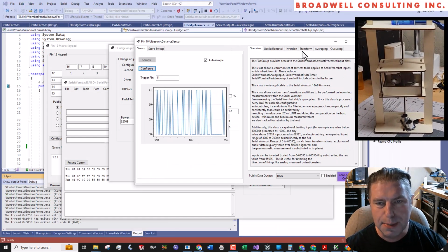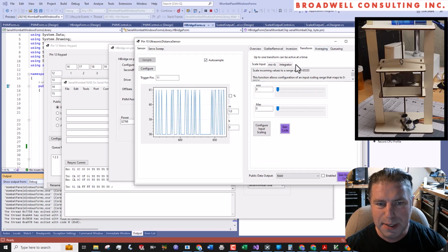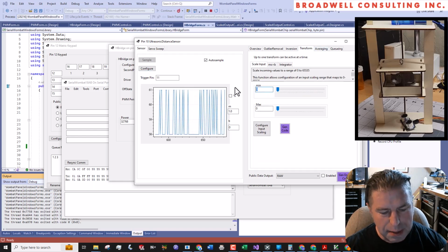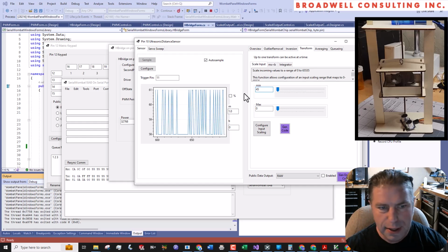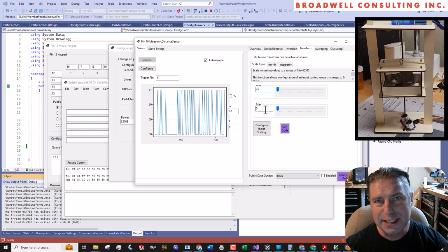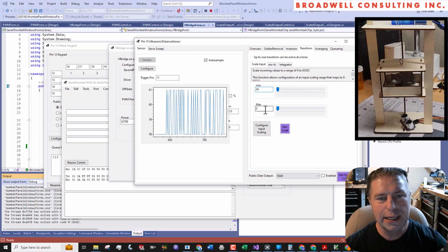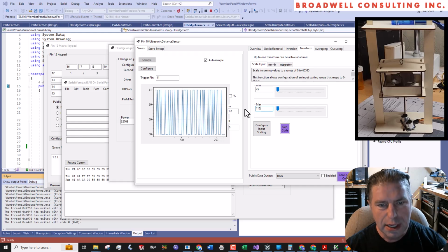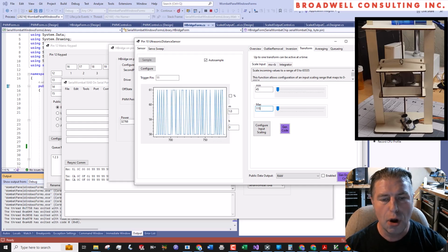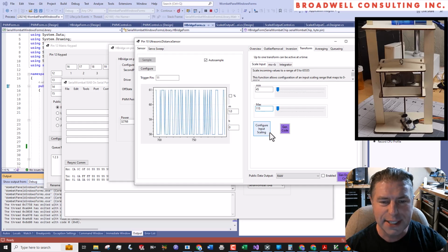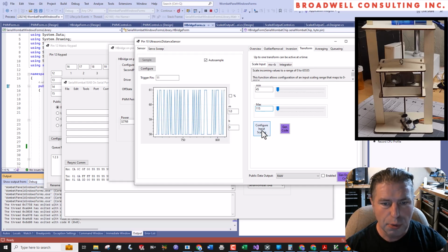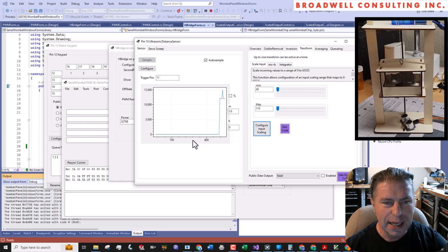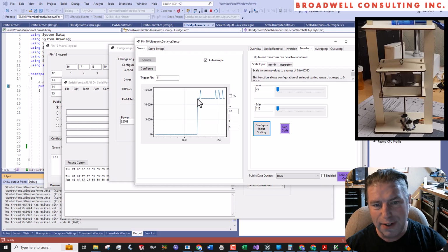For PID, typically I like to scale it from minimum to maximum. And we're going to have a minimum of 45 millimeters. There's a limit to how close you can get on the sensor before it stops working and it provides a really wacky value. And I know that the elevator car can go up so that the bottom's about 11.5 centimeters from the sensor. So we'll use those for our 2 input scalings. And we can see right off the bat, okay, we've transitioned now from 45 to 115 to 0 to 65,535.